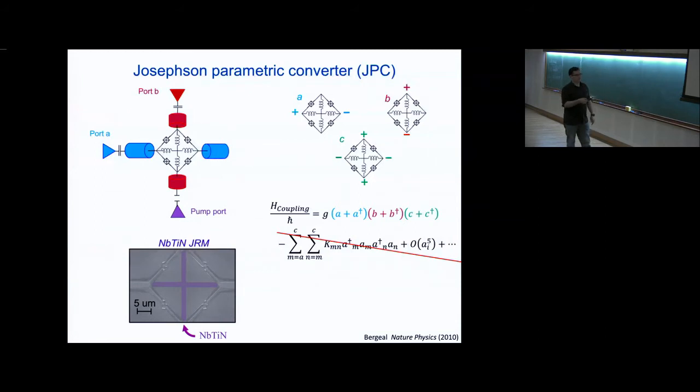So for reasons that'll become clear as the talk goes on, now we cross the ring with these linear inductors here. But the thing that powers the parametric part is just this 3-body coupling in the outer loop, which is the combination of this Wheatstone bridge shape and the applied flux that breaks the symmetry.